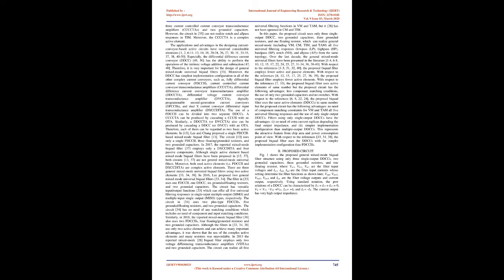In [32], the filter uses followers with a minimal realization. However, the filter in [32] still needs to use 7 current/voltage followers, i.e. 7 active elements, 3 switches, 3 floating resistors, 1 grounded resistor, and 2 grounded capacitors.